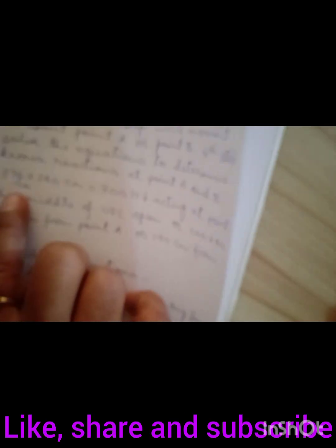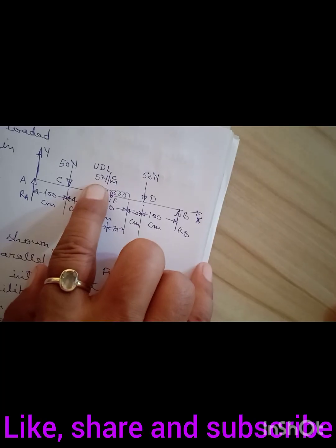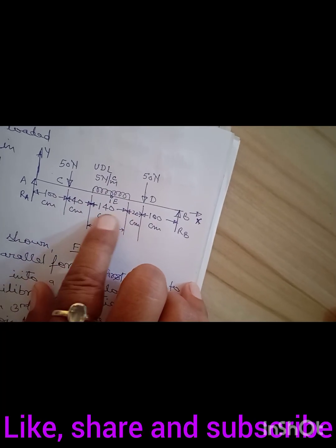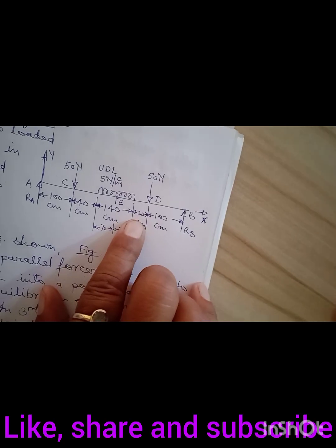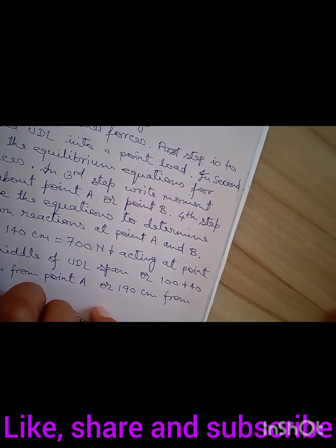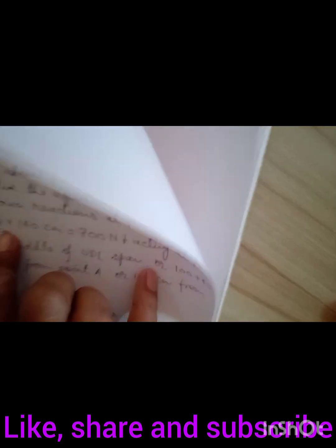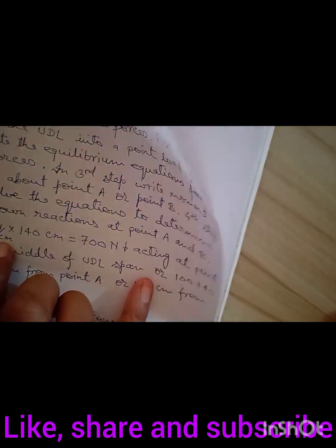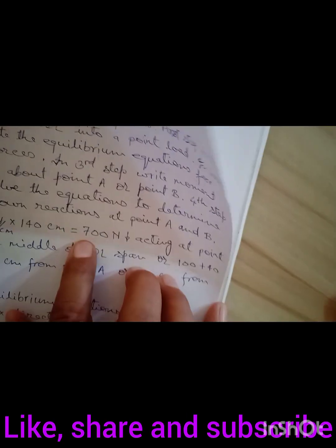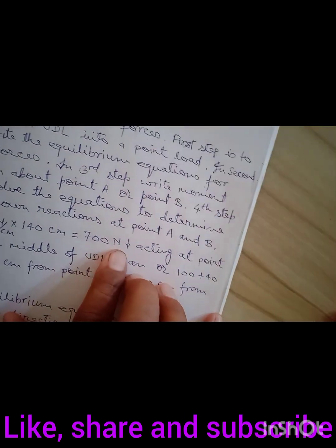So step 1: we can see that there is a uniformly distributed load of 5 Newton per centimeter for a span of 140 centimeter. This load is changed into a point load, that is 5 Newton per centimeter into 140 centimeter, as this is uniformly distributed, so 700 Newton.